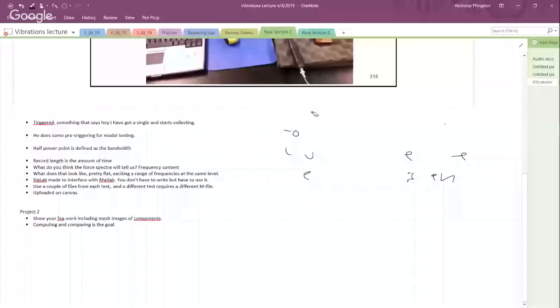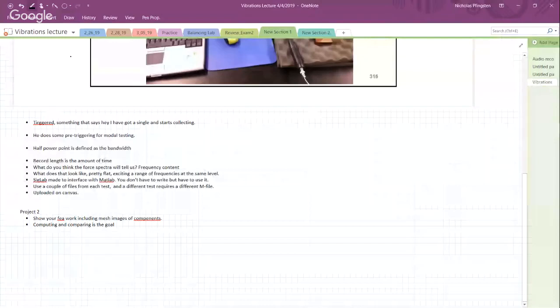There's one around 1400 hertz and another one just above. But I'd like you to also look at this one close to 200. I mean, I guess you could try to do something with those, but honestly, I'd ignore those. So look at this one that's about 250 here and here. So this first structure, you have 3 modes. All right.